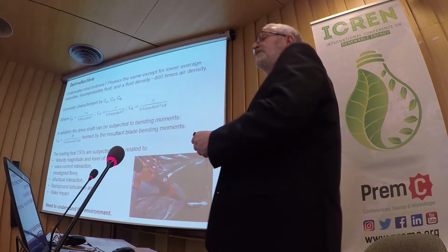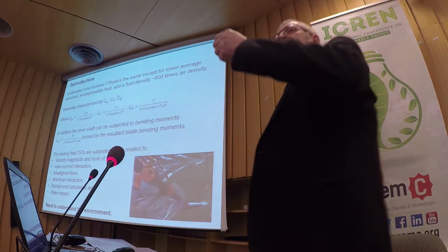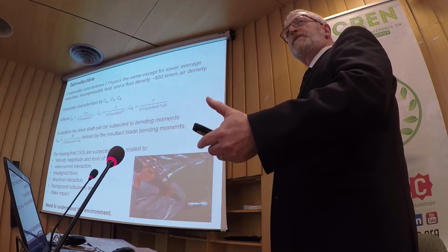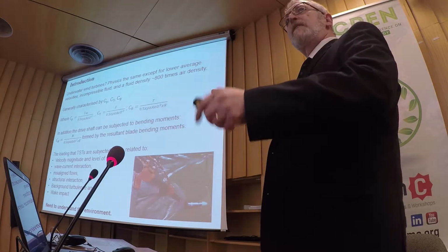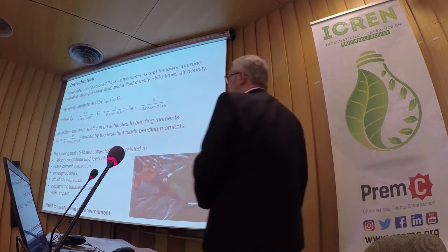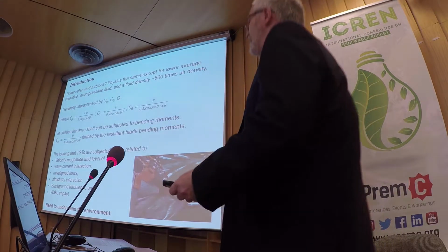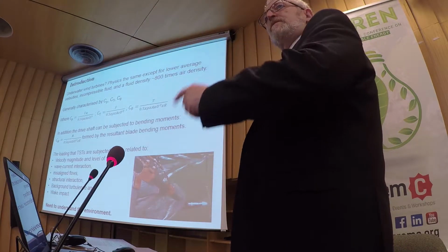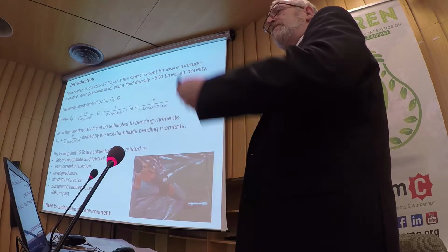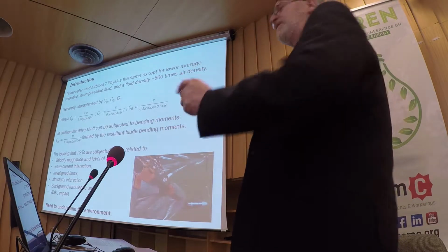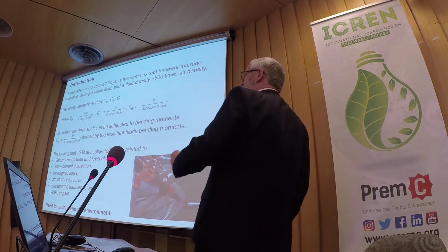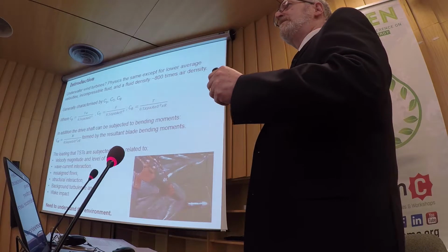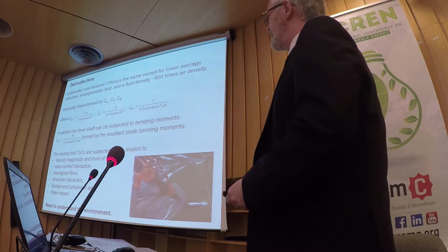So if you get a level of shear through the water column, you're going to have blades that are subjected to a higher velocity at one point than at a lower point. You're going to clearly get a bending moment occurring at the hub root. Wave current interaction. The wave that is 20 meters long, the penetration into the water will be approximately 10 meters. So it's about half the wavelength. That can have a severe effect on loading, depending obviously on the length or depth of the water.